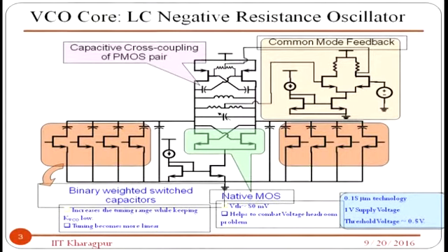With a 1 volt supply, there is a possibility that transistors would go to the linear region, even to the cutoff region, because it does not have enough voltage headroom. To avoid it, you can use low threshold voltage transistors in the cross coupled pair, where the typical voltage is 50 millivolt. Remember that low VTH PMOS is not available in the market.